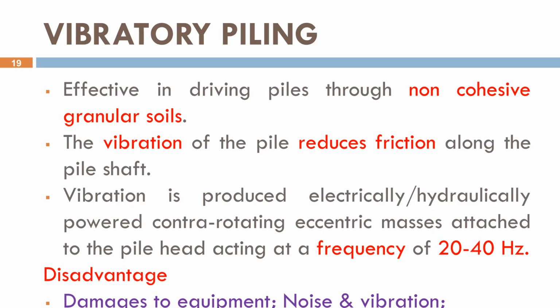Although this method is very fast, it has certain disadvantages. Continuous vibration may cause settlement of nearby buildings, generate excessive noise, and affect sensitive equipment. Therefore, engineers carefully evaluate surrounding structures before selecting this method.